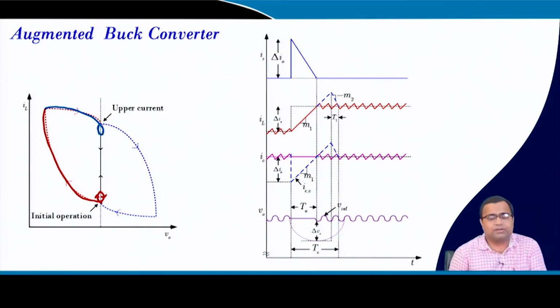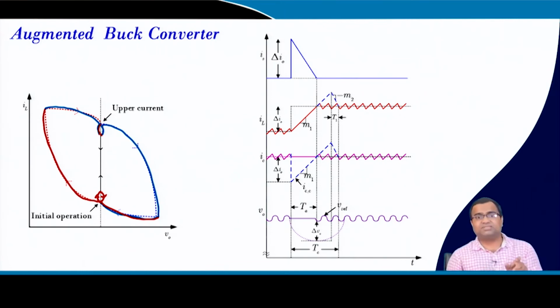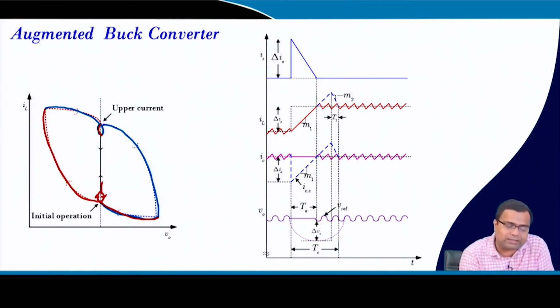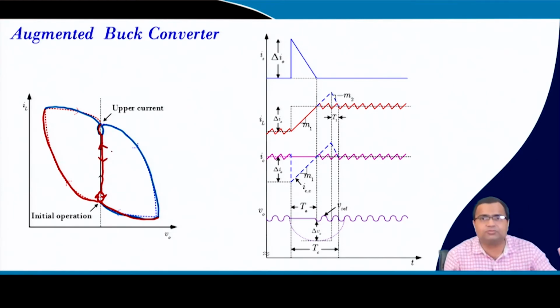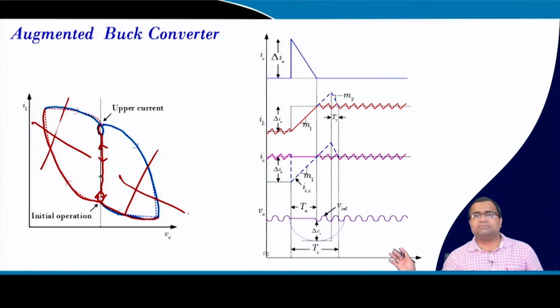So this is the first load step up transient. During step down, it is again coming here, hitting and turning off. This is the turning on path, in a different color. Here also, if we can provide this auxiliary path from one point to the other point, it will simply go like this, or it will simply come like this. So there will be no overshoot or undershoot, and this path can be discarded if we can make that ideal arrangement. There is no problem, but practically it is not possible.